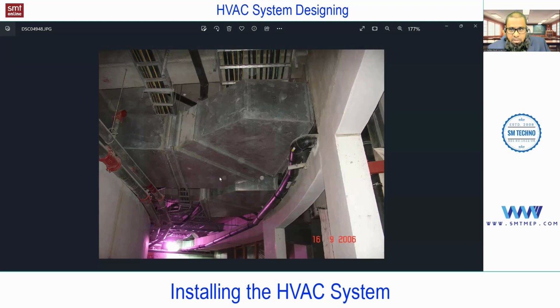You're talking about this image, right? You can see these cable trays and ducting. Your question is how to decide these levels, not positions. These levels are very important, because an issue in one level will affect all the services, and it's a very difficult job to accommodate. For example, a 1 feet false ceiling gap, and something like that.